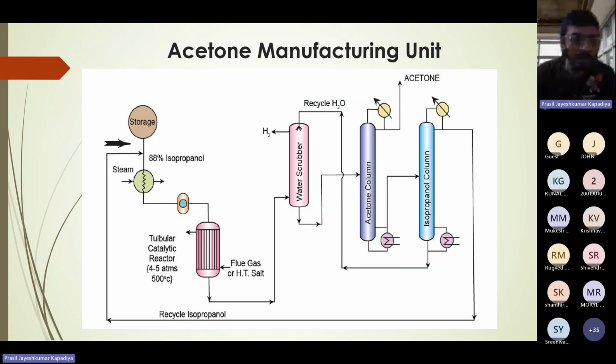We will have to play with the feed flow rate, the reflux ratio in the distillation column, and then we may have to increase reboiler duty. So there are options and the plant is already there. Let's say my feed flow rate is 100 and now I want to operate my plant at 130, 150. Can we do that?